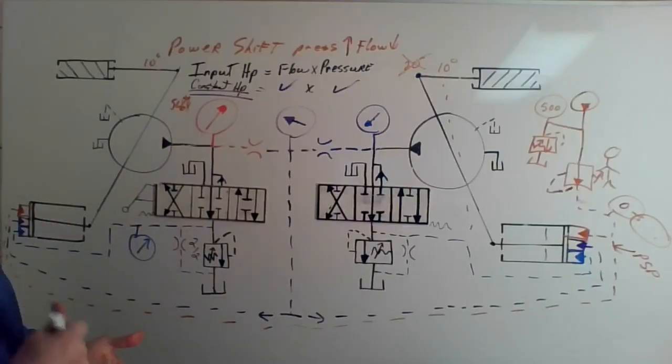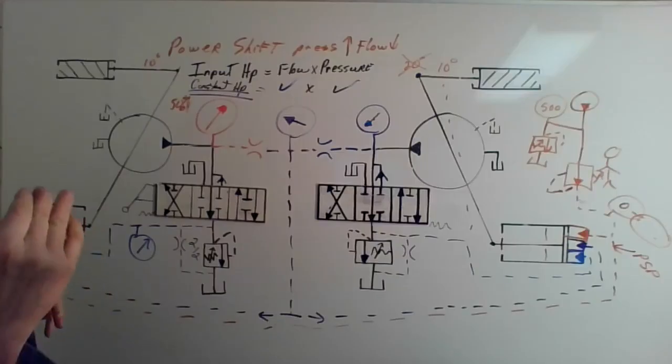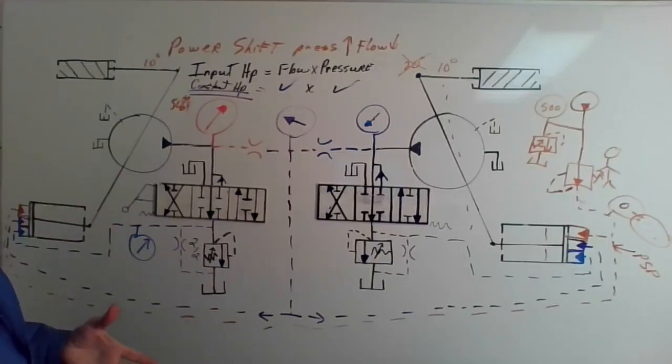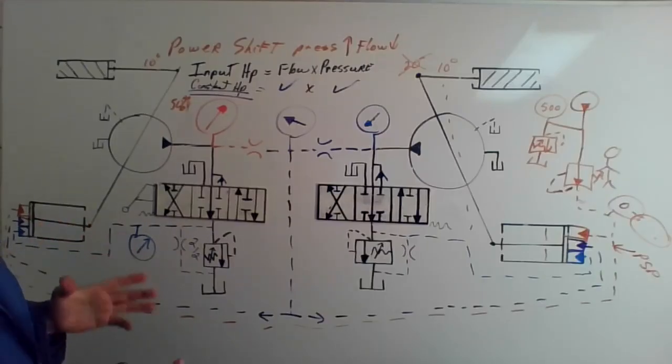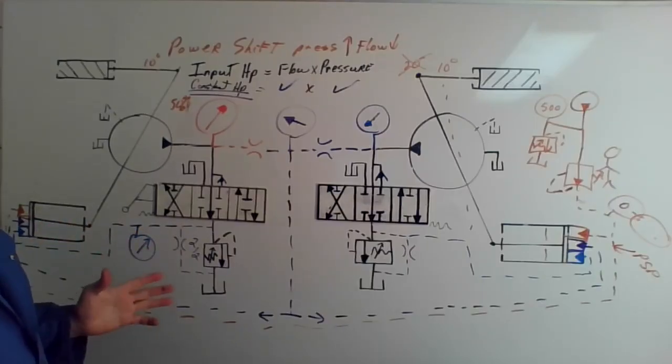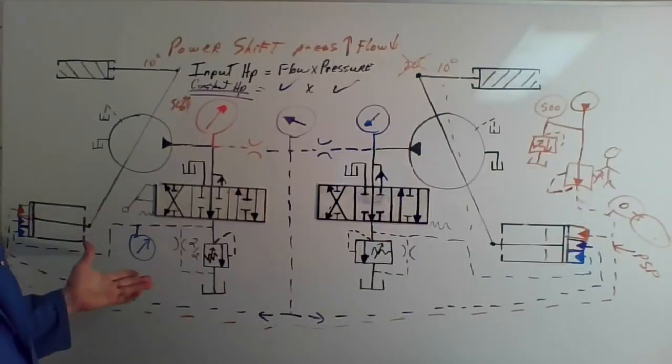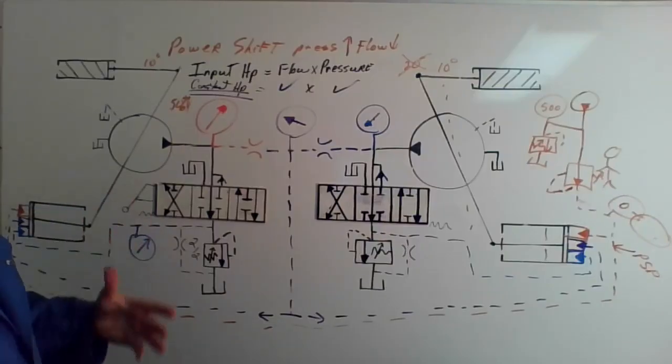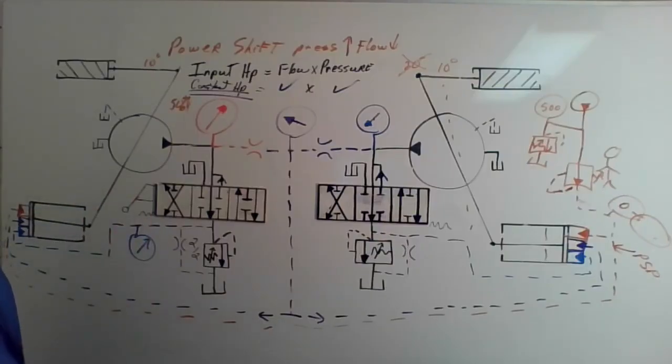So this is about production, production, production, and yet you still want to be able to physically lift something and generate enough force, and there's a lot of pressure on it. Well, then the pumps have got to back out of it. They've got to de-stroke, or they will hydraulically overload the engine. Fine, just back off in the flow, and you'll slow down, but you'll still be able to lift whatever it is you're trying to lift. That's the simpler side of that.